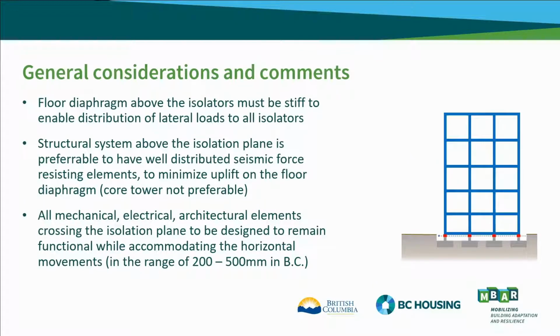The floor diaphragm above the isolators, above those red dots in the figures, needs to be very stiff to be able to distribute the lateral loads nearly equally to all the isolators. For the structural system above the isolation plane, it's preferable to have a well-distributed seismic force resisting system, not a core tower as you see in many buildings, but a well-distributed system, again, to minimize uplift at the top of that